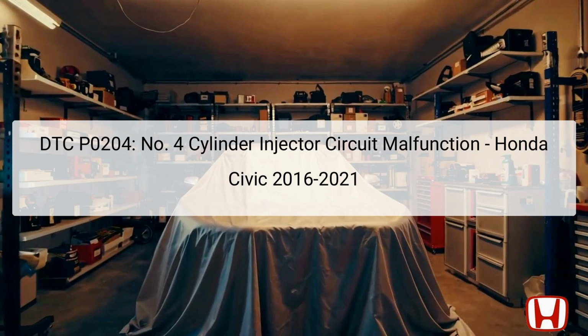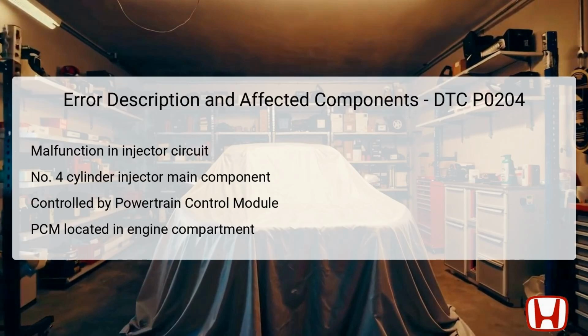If there is a malfunction, it can lead to poor engine performance, misfires, or difficulties in starting the vehicle. A thorough examination of the injector circuit is essential to pinpoint the underlying issues causing this DTC. DTC P0204 indicates a circuit malfunction related to the number 4-cylinder injector. This specific injector plays a crucial role in ensuring the correct amount of fuel is injected into the cylinder for